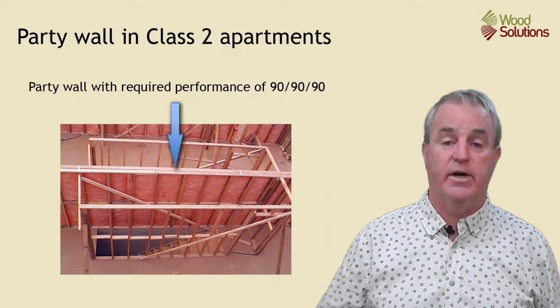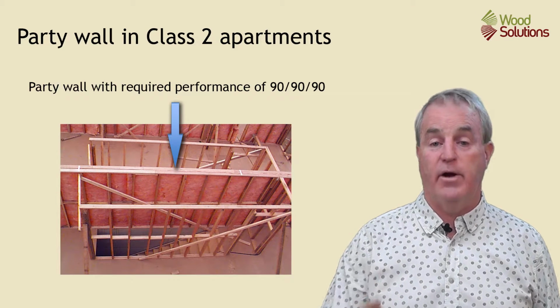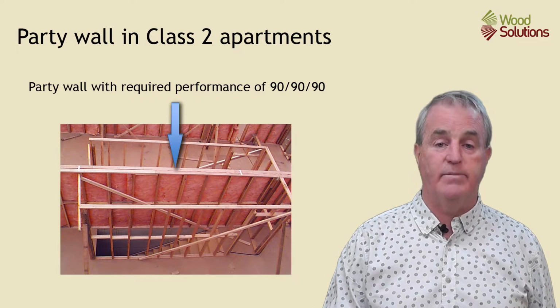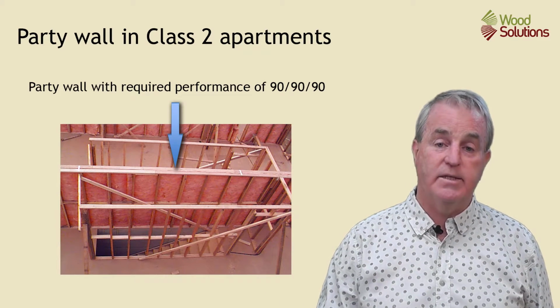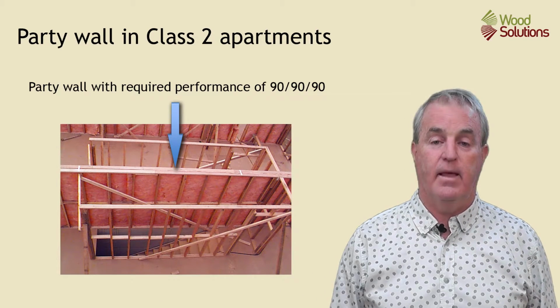of 90-90-90. This means that the wall must be structurally adequate to fire for 90 minutes. It must maintain its integrity and stop gases and flames going through it for 90 minutes. And it must resist excess temperature rises going through the wall for 90 minutes.